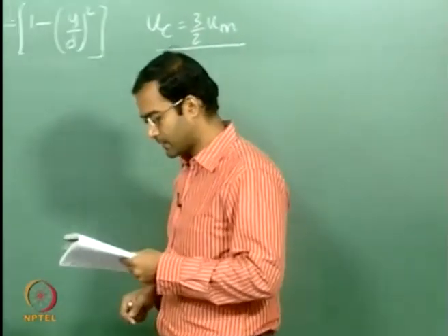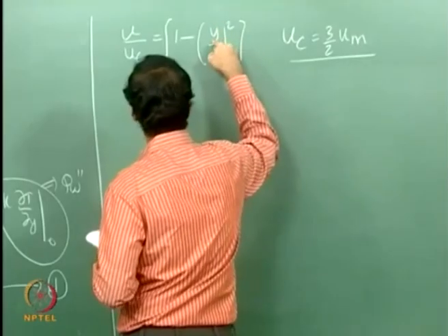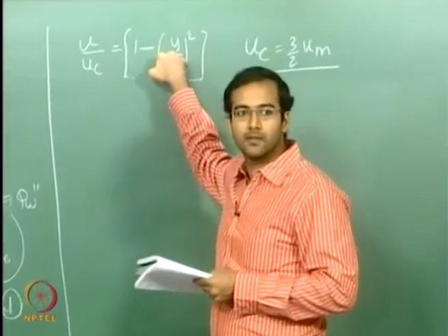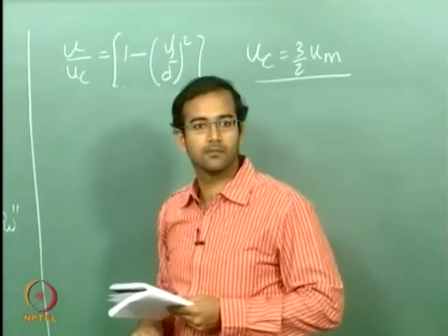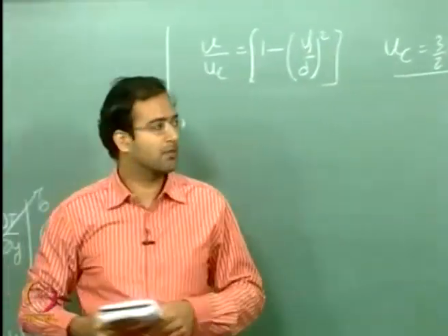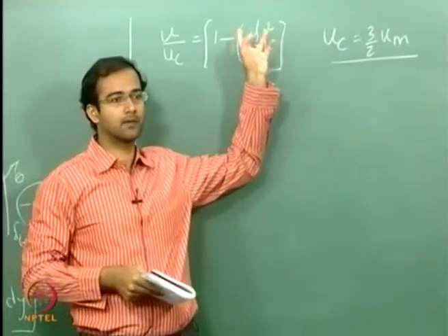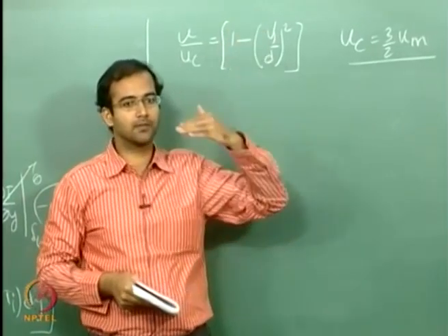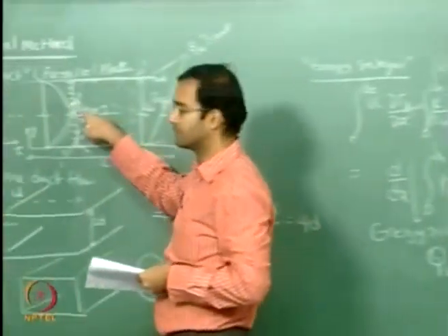So this is basically the velocity profile. Now this is written in terms of what? The coordinate system for this is from the center, okay, so therefore this is y prime. If you look at the profile at y prime of d and minus d, then this will be equal to 0, okay. That is only possible if the coordinate system is at the center.